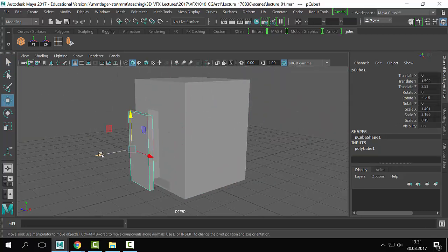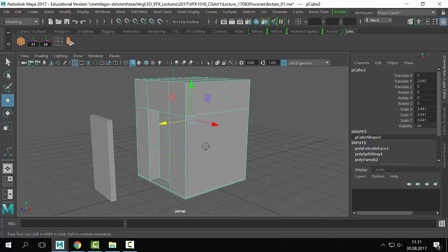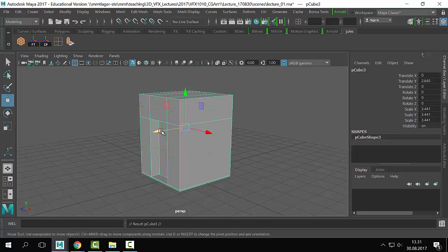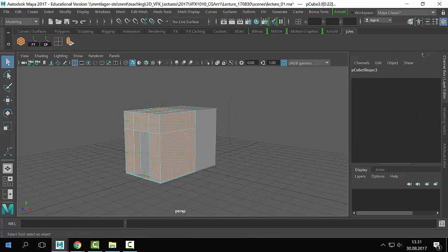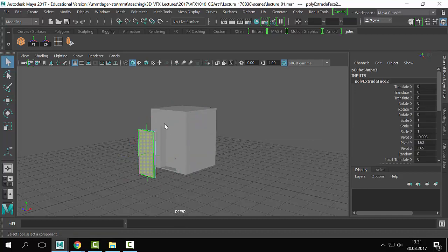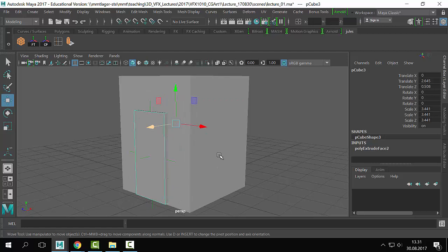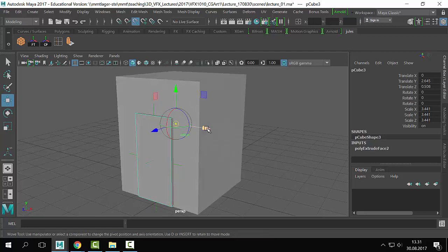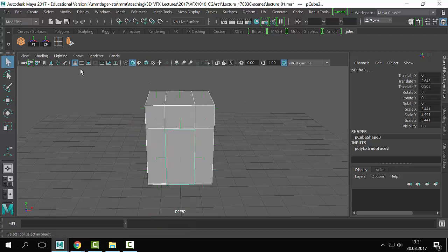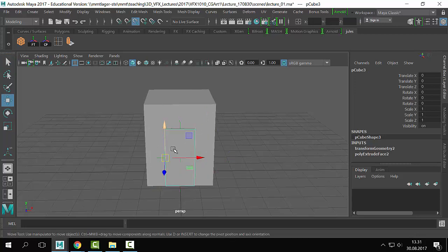I can put that in there. Let me show you a mind-blowing trick. How can I quickly make a door? Well, I can copy the mesh, select this face, and shift select the rest, and then I can extrude. And there's my mathematically precisely measured door, and then I can hold D and hold V, and then I can open it. Let me freeze the transformation, center the pivot, try again, hold D, hold V, snap, and rotate.